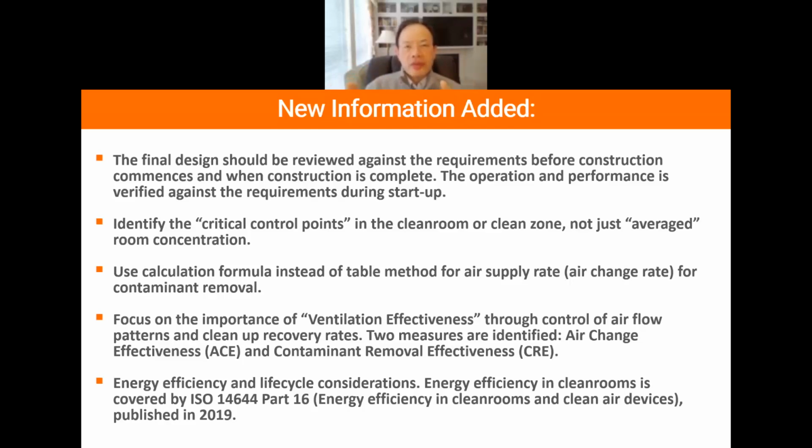These are the areas where the customer may need additional requirements. For example, for the room they may want ISO 7, but adjacent to this critical process area, they may want ISO 6 to give some additional margin or cushion to ensure that the critical locations will not fall below the ISO 7 level.